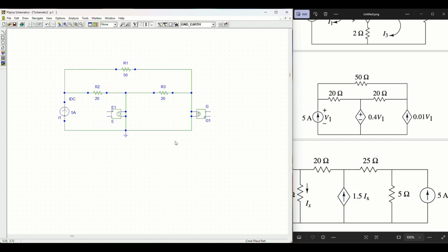Okay, so now next is what about this? In every component we can see there is an extra line, so to remove that extra line, just select that line and delete. In this way we do not have to draw one by one points, we can directly first make all the circuit connections, then we put the components. So now we have eliminated all the extra lines.